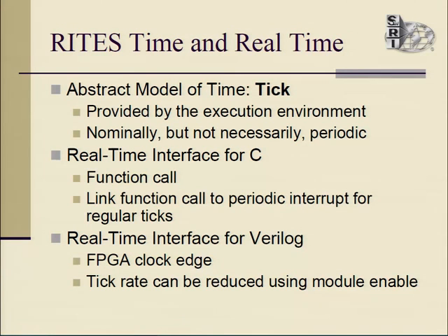If the timing language module is implemented in Verilog, that tick is an FPGA clock edge, which of course is strictly periodic. Often very fast. We have a mechanism to slow down the rate of ticks with an enable input to those modules. Not really necessary. The only reason you want to do that is if you have relatively long delays and you don't want your counters to get too big. It's a means of doing that.